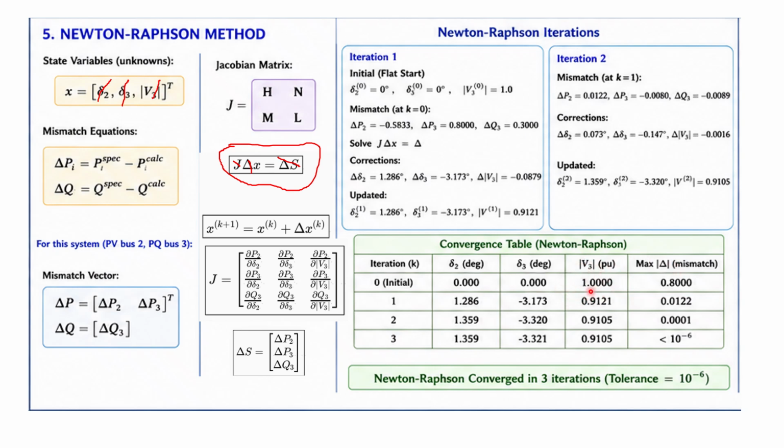So during that, the maximum power mismatch is obtained. So here, what we'll do is calculate δ2, δ3 using the first iteration mismatch. The mismatch is obtained by taking the specified value and calculating the magnitude of power at that bus by using the flat start and taking the difference.